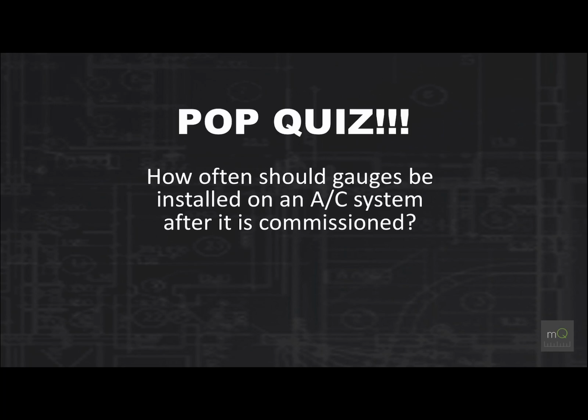If it's not cooling, I imagine the last thing you're going to do is run out and get some piercing valves and tap into your sealed system and see what the refrigerant pressure is before you do things like clean the condenser or make sure something's not blocking the evaporator or making sure nobody left open their freezer door, right? It's basic stuff. The last thing we want to do is check charge in a sealed system.